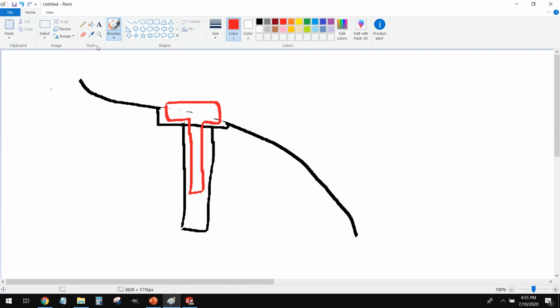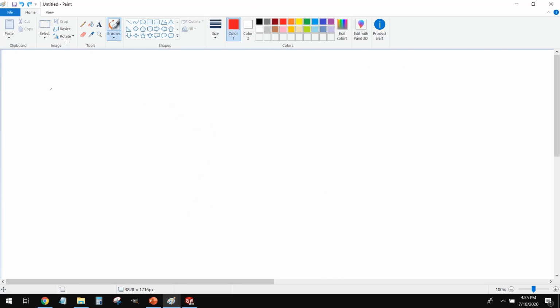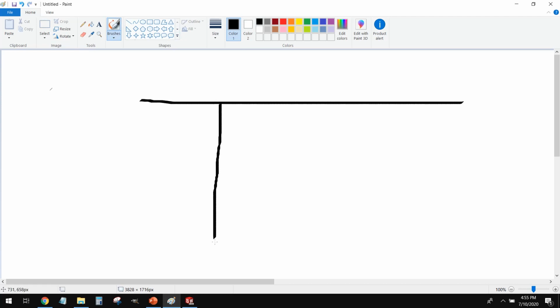And to explain that, I'm going to go back to my fancy modeling software here. When you drill a hole to be tapped, you're going to drill that hole out. And then when you run a tap through here, that tap is slightly tapered.